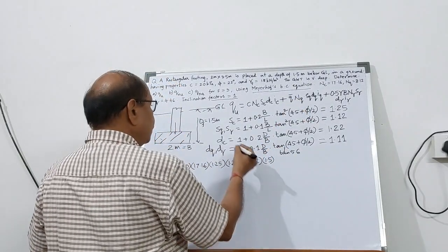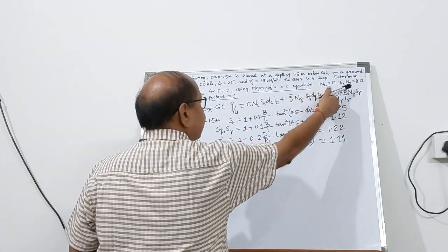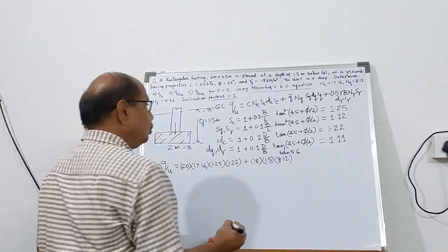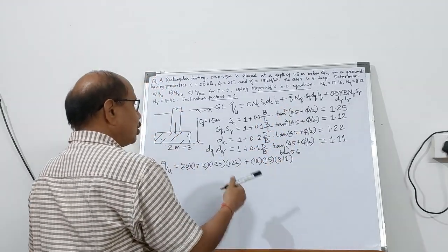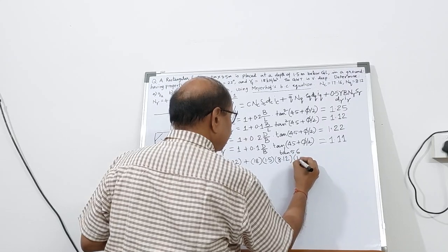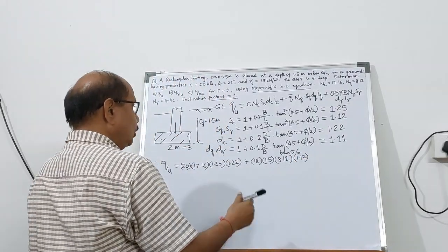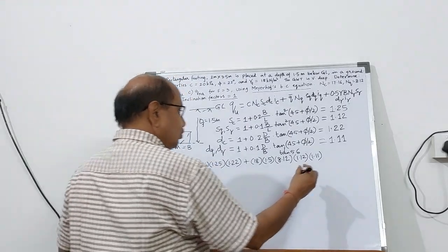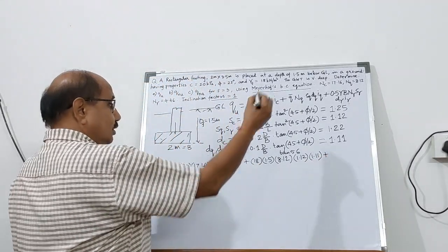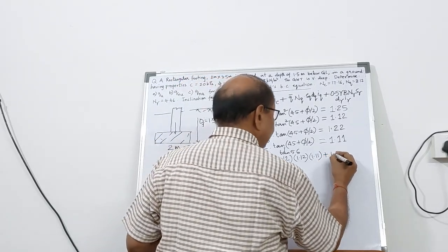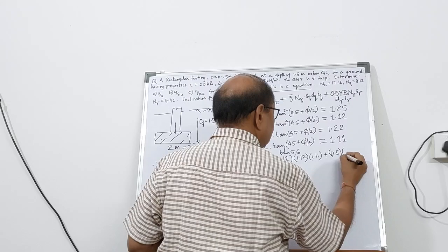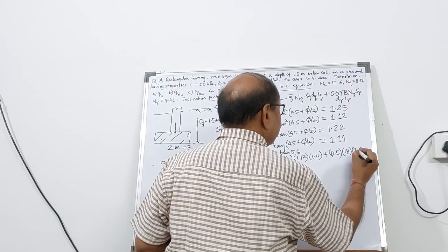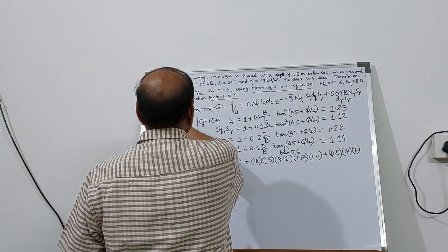multiplied by NQ. NQ we have calculated. It has been given as 8.12. The shape factor SQ we have calculated as 1.12. DQ has been calculated as 1.11 and IQ is 1 plus. The third term is 0.5 into gamma, that is 18. B is 2 meter. N gamma is given as 4.46.